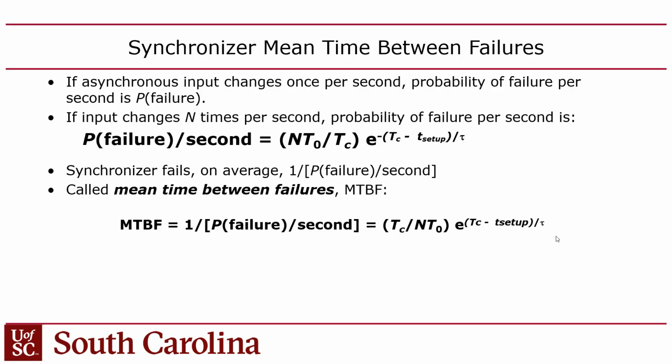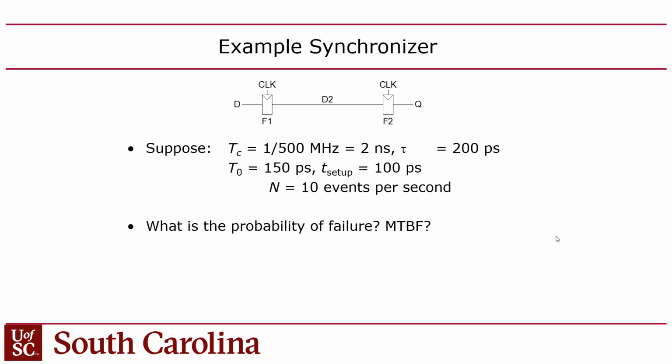So if you're designing an interconnect like UART, you might want to put a parity bit in there, right? That's what the parity does on a UART channel, is accounting for this metastability, right? Or you may need some other kind of error detection mechanism in any kind of I/O. You know, chips talking to one another, they don't share the same clock, and thus they can't guarantee the dynamic discipline. Okay, so here's an example question for that.